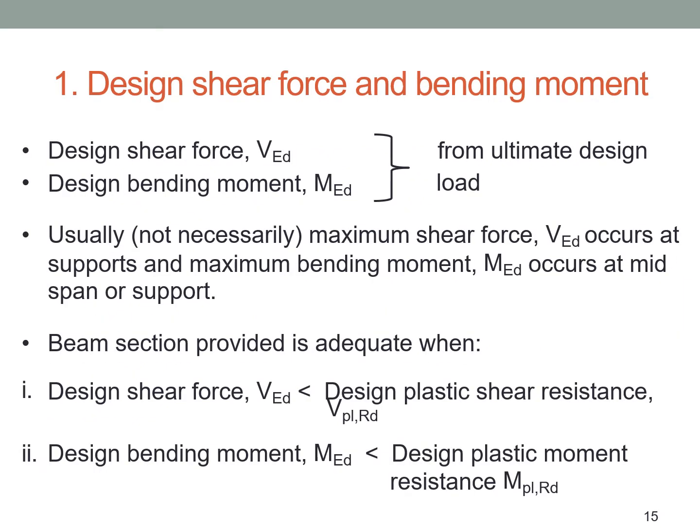Let's recap from the previous lecture, design shear force and bending moment. The beam section provided is adequate when the design shear force is less than the design plastic shear resistance, and also the design bending moment is less than the design plastic moment resistance. In today's lecture, we are going to calculate VPL-RD and also MPL-RD.